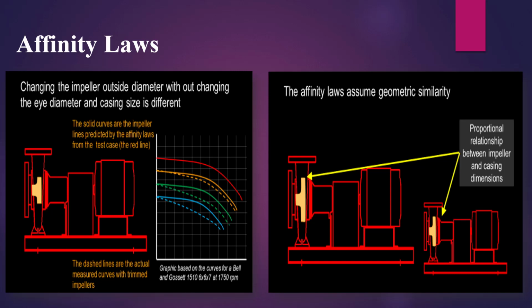Pressure is proportional to the shaft speed, squared. So with half the shaft speed, you get a quarter of the pressure. Let's say you were getting a pressure of 100 for a shaft speed of 10. For this example, the units of pressure or speed don't matter. 10 squared is 100. Now let's reduce the shaft speed to 5. 5 squared is 25. Half the shaft speed, quarter the pressure.